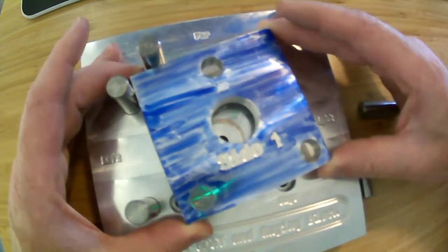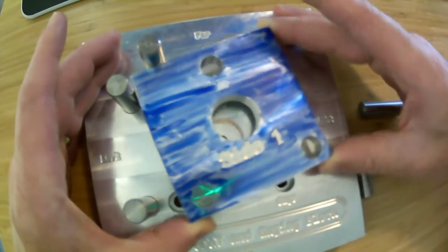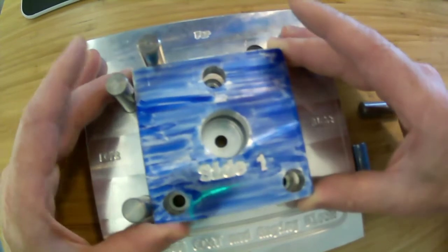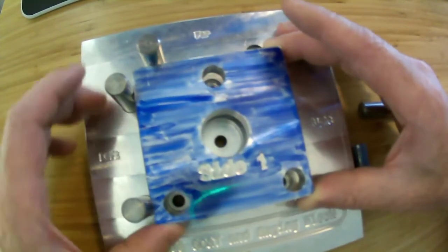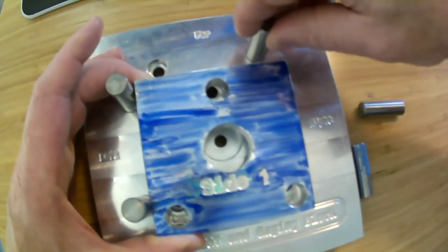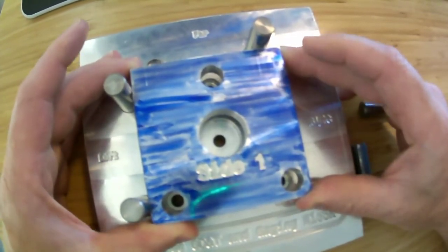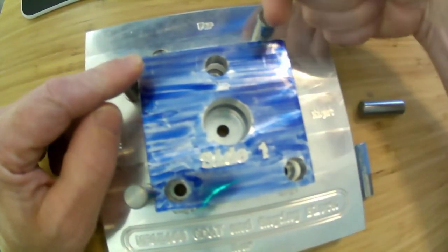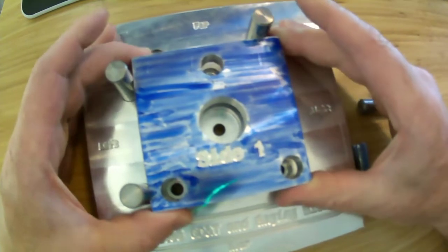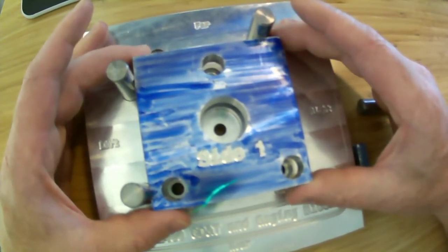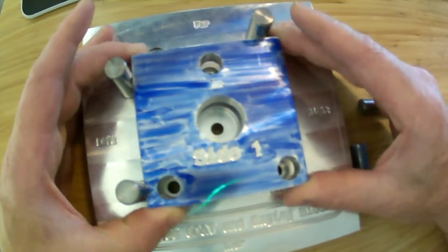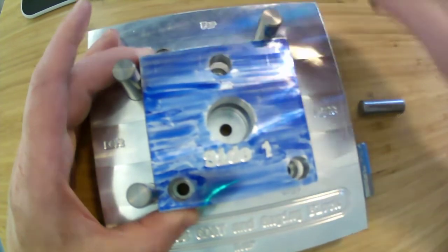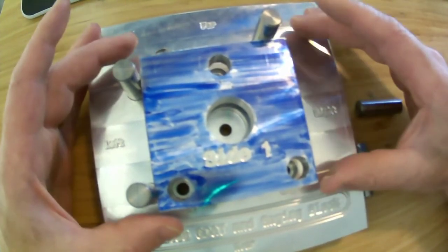And the reason is this. See how easily the part rotates around these 2? It kind of uses these 2 as a hinge, and it can rotate off really easily. So it's not very stable. If instead I had put this dowel over here, then the moment from this contact point to where this dowel is applying force is much larger, and so it is generally a better place to put it. In fact, now these 2 kind of act as a hinge, and so sometimes I might want it to sort of be in the middle. Again, it just depends on how I'm going to load it.